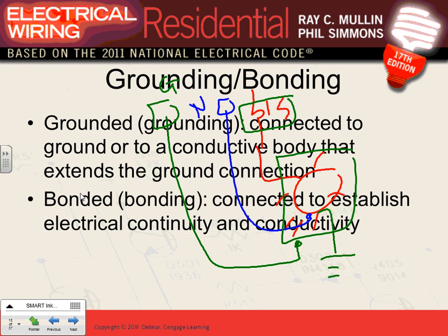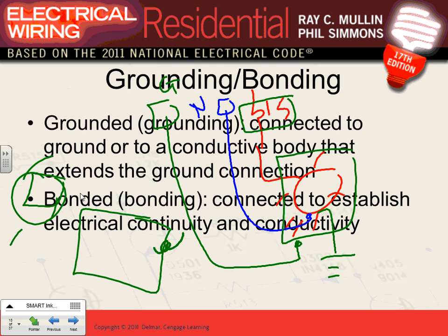Now bonding: the way we bond things that are electrical, or things that are non-electrical that could be energized. Suppose you have a tank sitting right here, and it has nothing to do with electrical, and right next to it is some pump. At one point, that tank could be energized, right? So we grab a wire and take it to the ground to bond that tank. Water heaters, we bond water heaters. All the stuff that we have, we bond it.